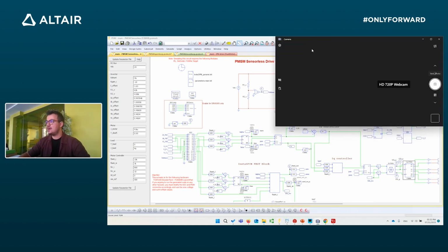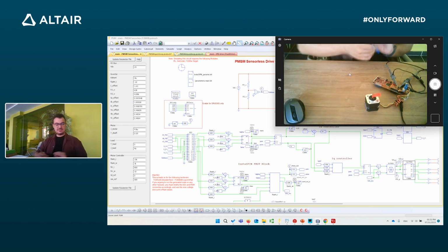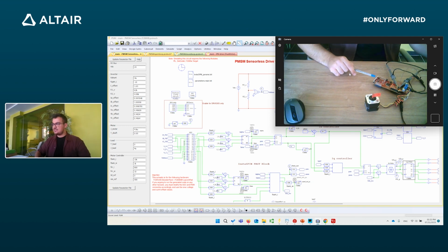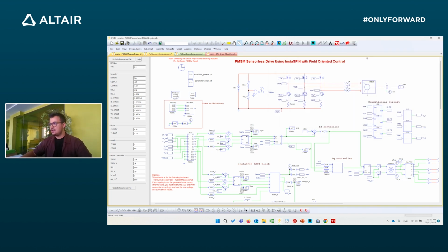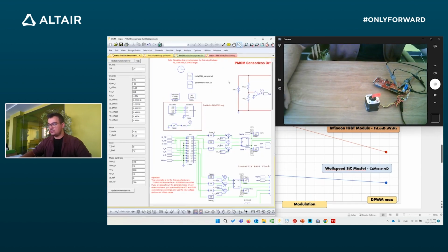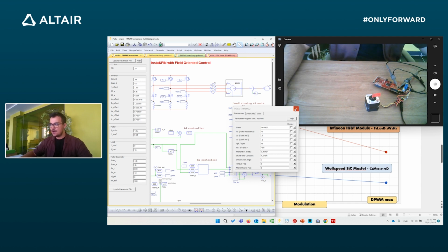for the actual hardware I have in front of me, so here is the motor. Here is the MCU, the brains of the system, and upon the MCU is a small motor drive development board, again from Texas Instruments. So for this system, I have modeled the motor parameters inside PSIM. This is the motor model I have used. It's just a linear one in this case.